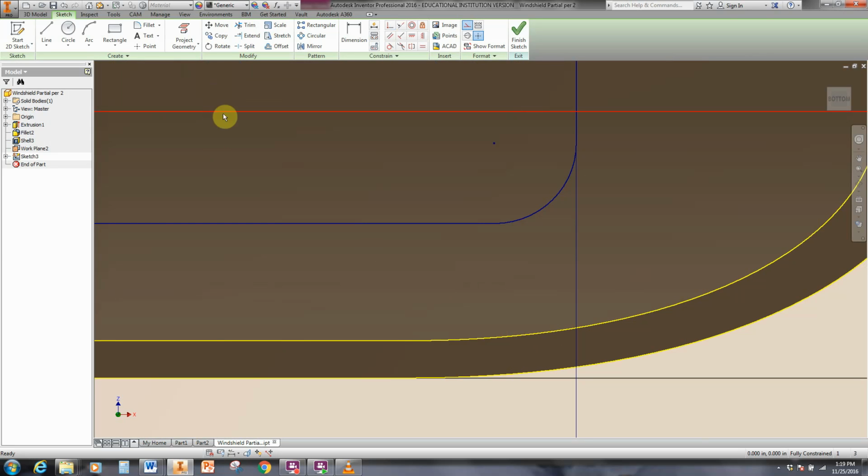Now we're going to draw another little rectangle down here. This rectangle has the same dimensions, but it's oriented 90 degrees from the previous one. Again, I'm not choosing the exact spot, but I am going to type in the exact dimensions. 0.05 is the width, and it sticks out from our rectangle that we drew, 0.04. And I click enter.